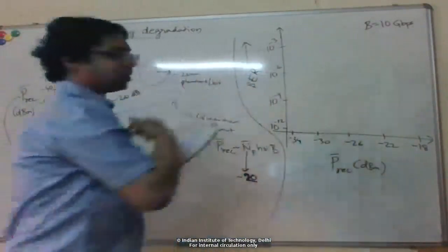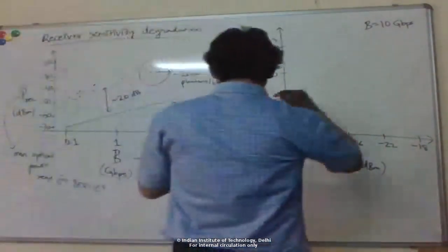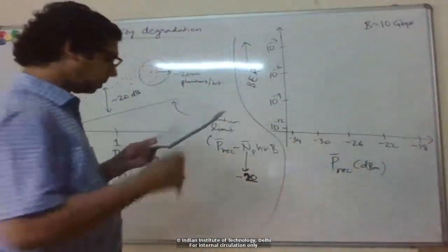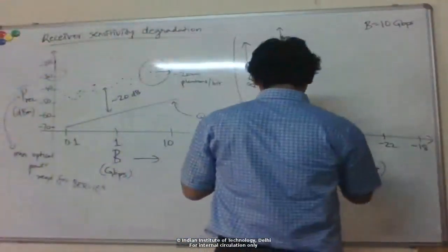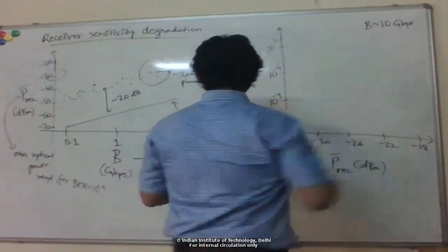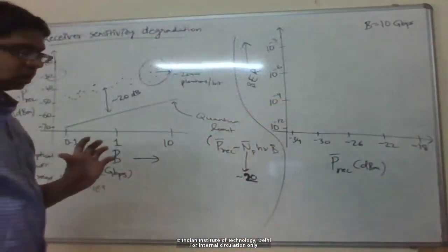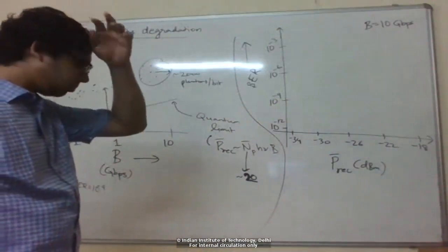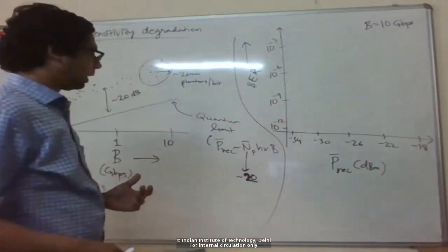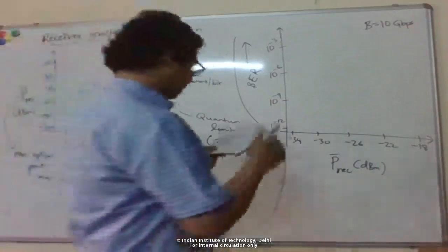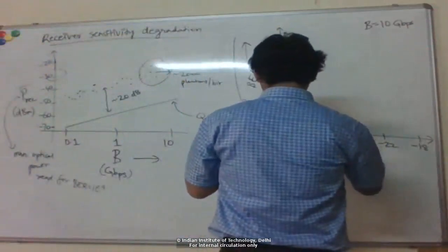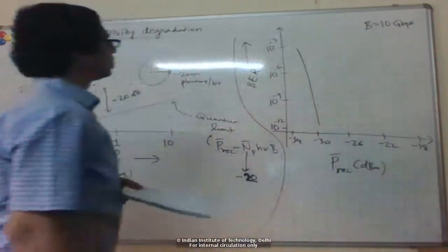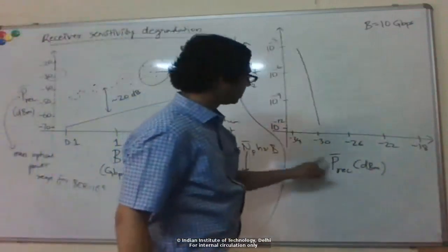So now we can plot this curve for different link lengths, for example. Okay, so if you have a very short link, so that you don't need any amplifier in between, so a few kilometers maximum, then there you are limited just by receiver noise, right? There are no other noise sources because you don't have any amplifiers in between. So in a sense, for a very short link, your power penalty is the minimum. Okay, right? So that looks like that. Okay, so the BER falls quite steeply with small increases in the received power.